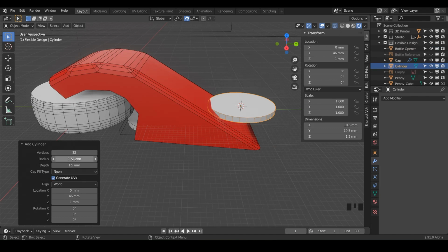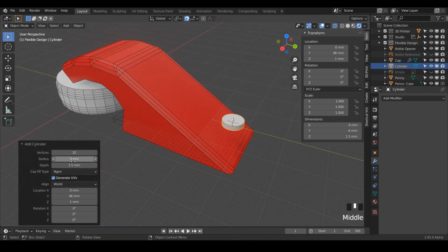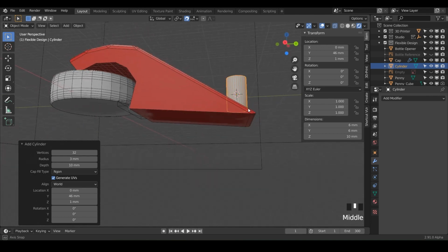And most keyholes are about 5 millimeters in diameter. So we'll just put 5 divided by 2. And that may be a little small, so I'll do 7 divided by 2. However large you want your diameter to be. I may just do 3. So we have a radius of 3, diameter of 6 millimeters, and the depth we can just do like 10. And there we go. So now we can use this to cut a hole.